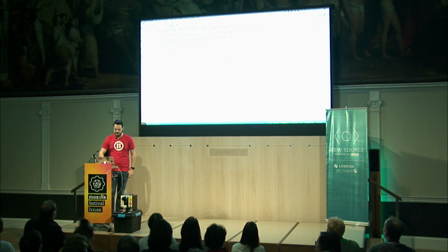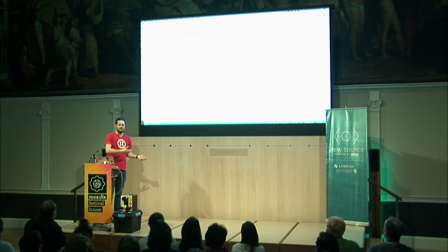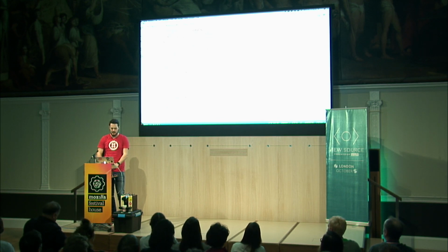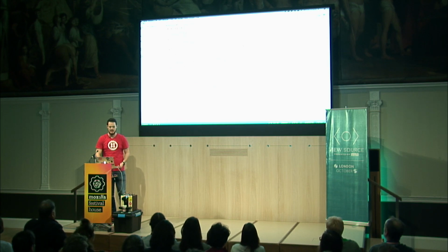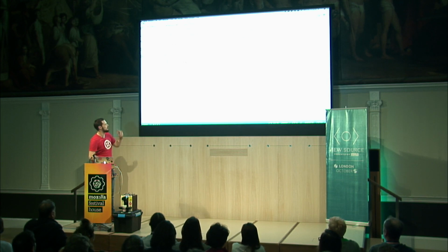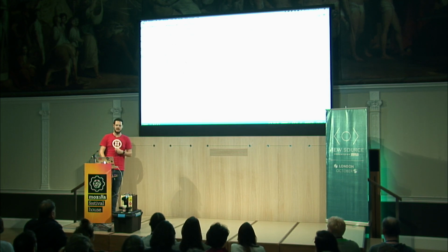So I'm going to show you, in the meantime, how the actual interaction works, because so far I only showed you the web server. The actual way I'm interacting is just like the demo script that I showed earlier. So I'm creating here some relays once they're ready. And in order to press the buttons, I have a press button function here. All that does is it opens the relay. And then after 500 milliseconds, it closes the relay.